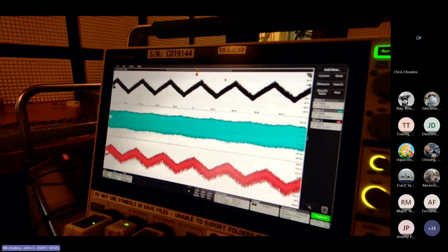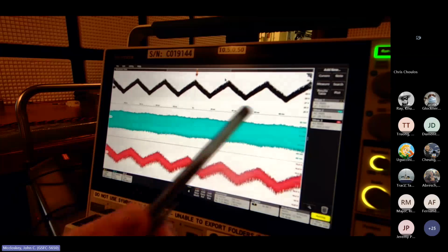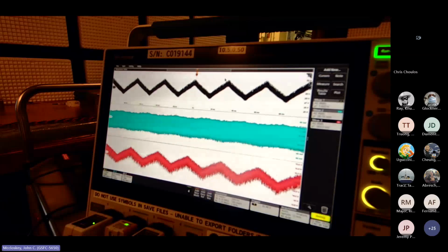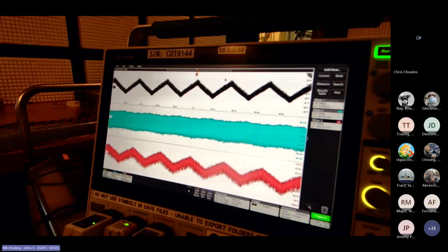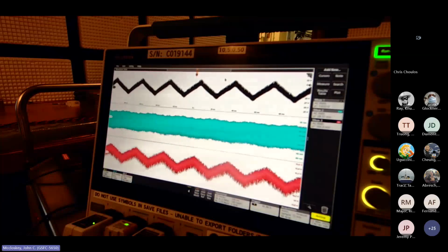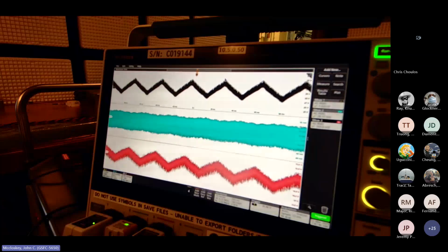It just so happens that what I set the signal generator to, the signal level is minus 13.8, but we're getting right around 1 volt AC RMS on our input. So that is about our desired injected signal level. And the current just has a lot of noise riding on top of it. It's hard to get a meaningful reading, but it says 28 millivolts.